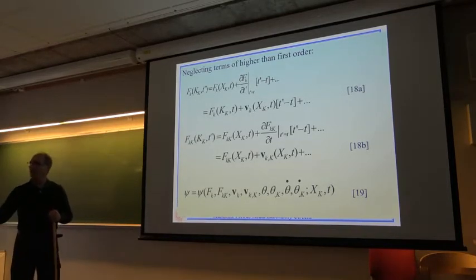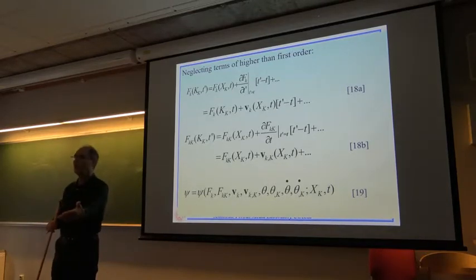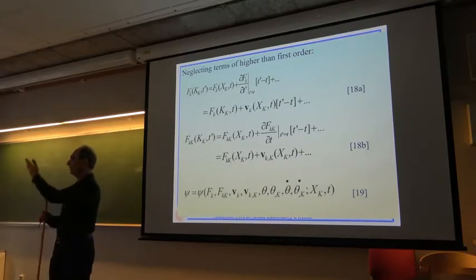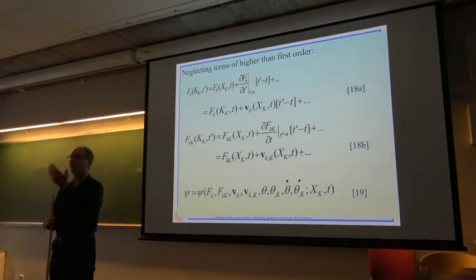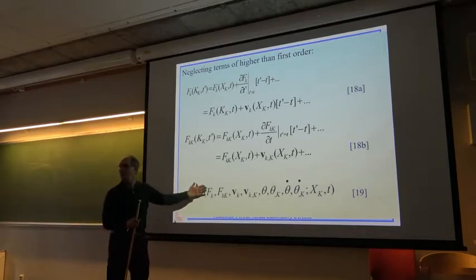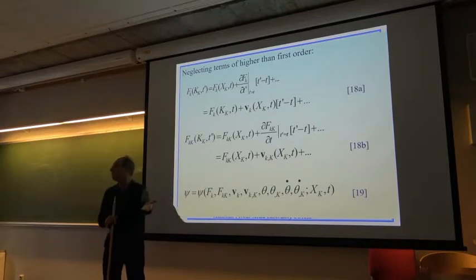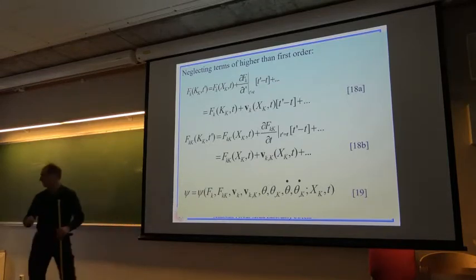What we will do is the following. We take this and put it through the procedure. At some point we come up with a set of constitutive equations that tell us this is how the material behaves. For example, if it behaves as an ideal gas or a viscous fluid. And then we say, yeah, but my material is not doing this, it's more complex. No problem. We come back here. What did we throw away? We have to put it back. That will give you a more complex material constitutive equation.